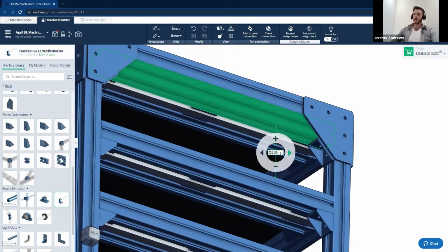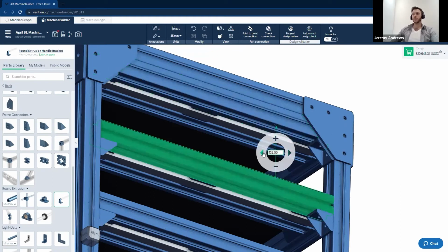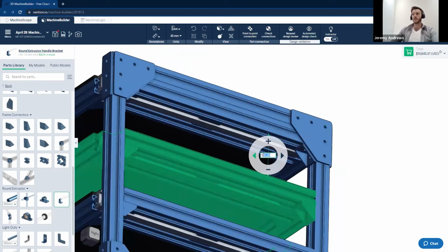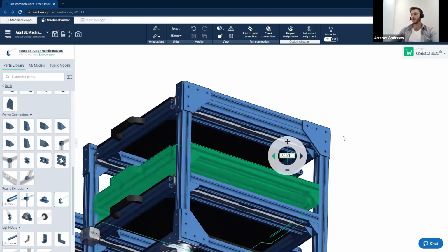Then you click on the measurement itself and cycle through using the arrow keys. Any part that is highlighted will be the part that is then moved when using the Smart Dimension tool. In this case, I can use either the plus or minus arrow keys over here, which will then jump my design in the snapping increment that I've chosen, or I can use a value that I can input by simply typing on my keyboard. In my case, I'm looking to have this spaced out at 180.